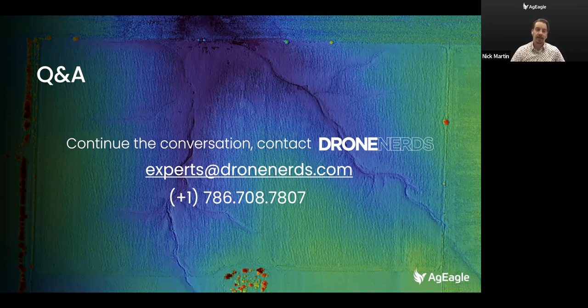I think of it as a sixth band. The RedEdge-P is a 5-band sensor, but the panchromatic band is like a 6th band. So it's a black and white image. And when you go into post-processing, it'll take that black and white image information and just combine it with either a blue or a green or a red picture taken on one of those wavelengths. And it'll merge all that information. So you end up with a lot more pixel information than you otherwise would.